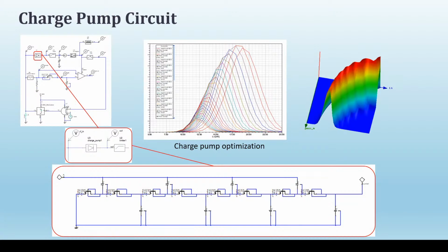You can do it this way, and you can also set up parameters, or you can set up optimizations. So to optimize your charge pump, you can locate your desired result, let's say with different inductance. So you can set up the optimization for your charge pump as well.